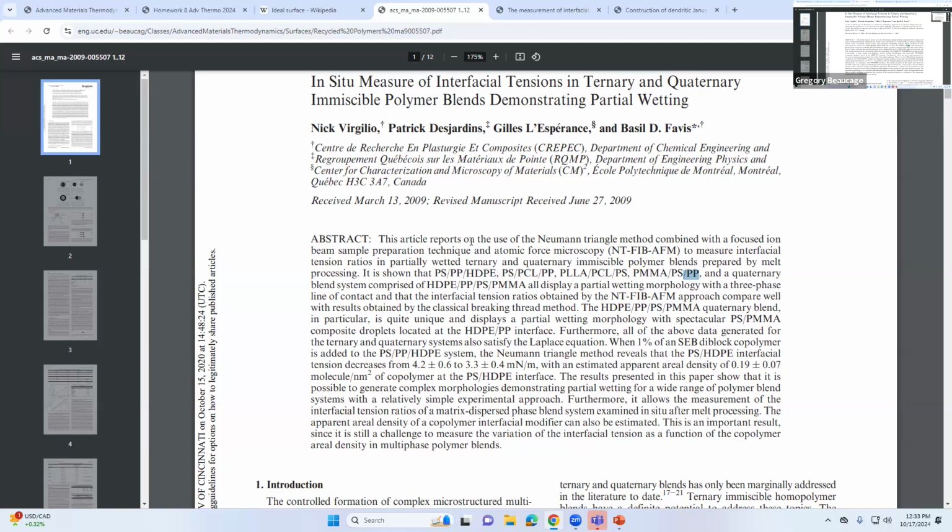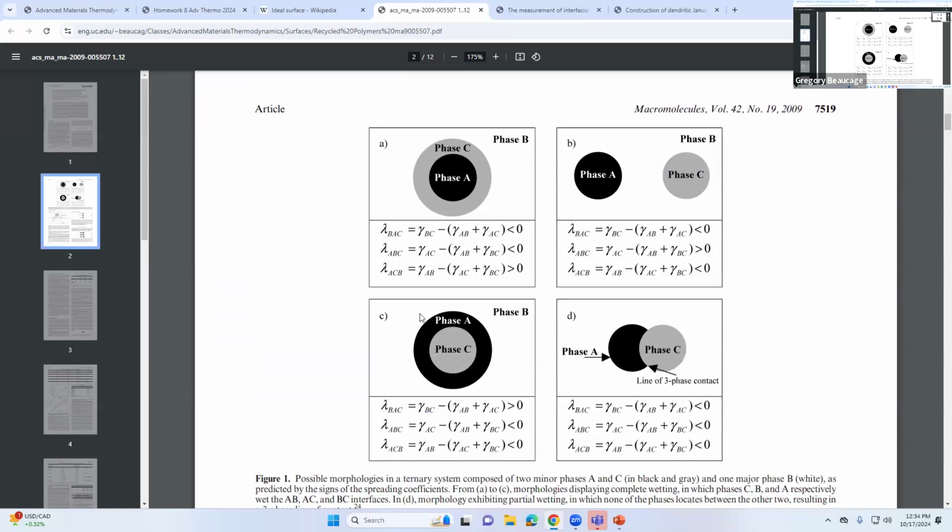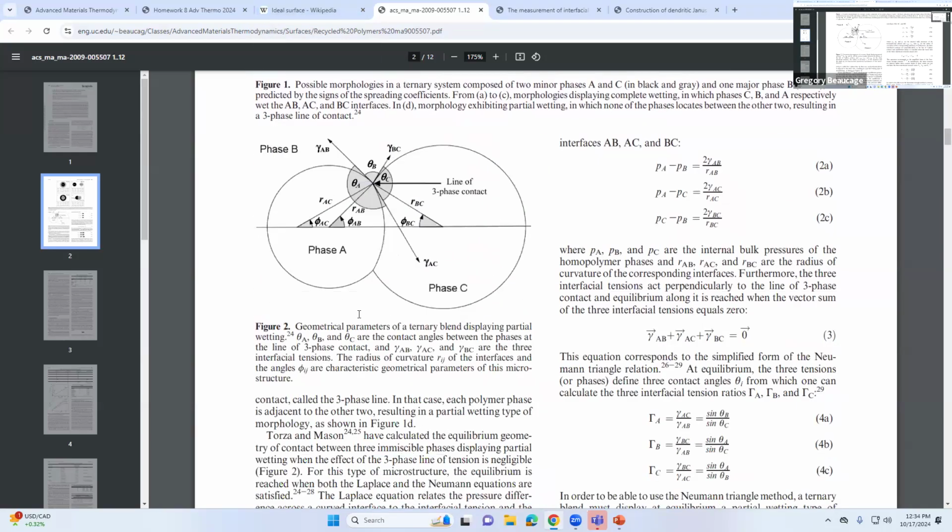So when you get the garbage, again, this is going to go to the recycle place and they grind it up into shreds, like Rumpke Recycling on Vine Street. And then they have a pile of shreds that are mostly polyethylene and then like 25% polypropylene. So the problem is polyethylene doesn't mix with polypropylene. In fact, no polymers mix at all. There's a couple, but basically there's none that mix.